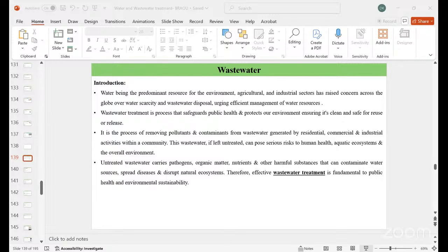It has an inlet and an outlet zone. The inlet distributes incoming water evenly and minimizes the turbulence that could disturb the settling, and baffles are also often used to control the flow. The outlet zone is mainly designed to collect the clarified water without disturbing the sludge.